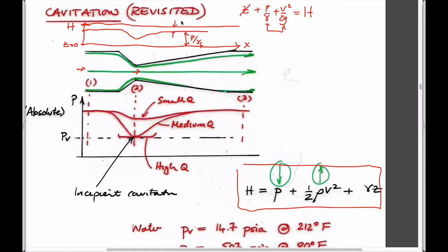And this, as you could rationalize, would be the velocity head, V squared over 2g, and so on. And so clearly at this point here, velocity is increasing at the expense of pressure, and then it regains this, where as velocity reduces, then pressure bounces back.